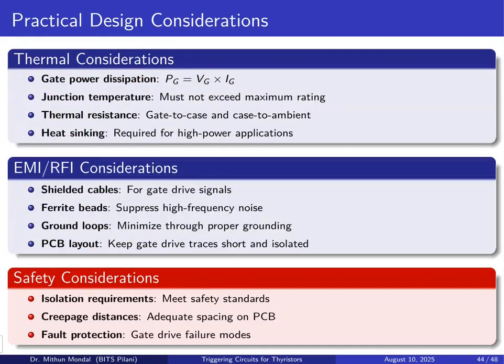Again, we need to do the thermal consideration, the EMI and RFI consideration, and some safety considerations. This is important when we are properly designing the network, and these considerations play an important role. We need to pay attention to parameters such as cables or ground loops, the layout, and safety considerations in terms of isolation, creepage distance, and fault protection. This will be used in the design phases.